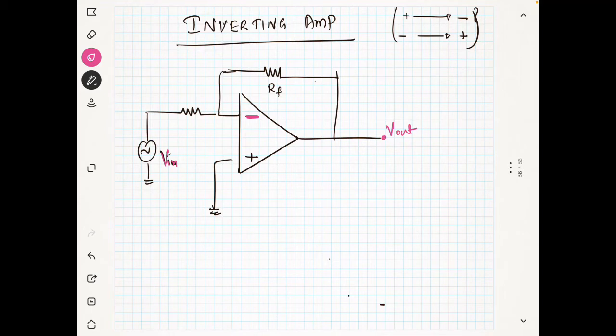Now I told you that this is directly connected to the ground, so we will do the circuit analysis. Now this is 0 volt, so this is also 0 volt. Now what will be the voltage here? Let's say this is some voltage VA. Now I told you the current going into the op amp, let's say this current is I2, which is equal to 0 ampere, because current going into the op amp is 0 ampere. I can apply the KVL in two different ways. Engineer Abdurrahim will be teaching you maybe one way. I will give you two ways, both are same anyway.